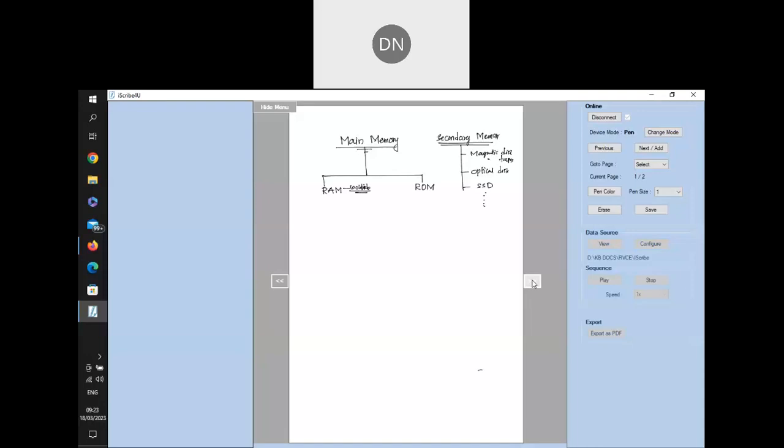It is the same with memory bits, always flip-flops also. When the power is lost, the flip-flop data will go. When the power comes, some data will be there in the flip-flop, but it is not valid data. Some random data comes into the flip-flop, as we have seen in the lab experiments. Similarly, read-only memory is non-volatile, in the sense that whatever program is stored in this memory will be there even when the power is lost. Both of these memories will have the same characteristic called random. So I can use it.